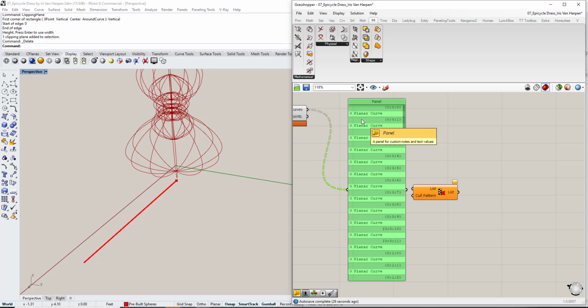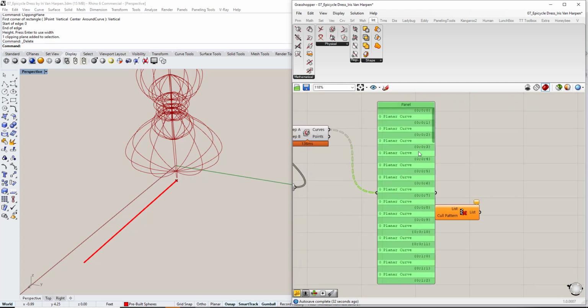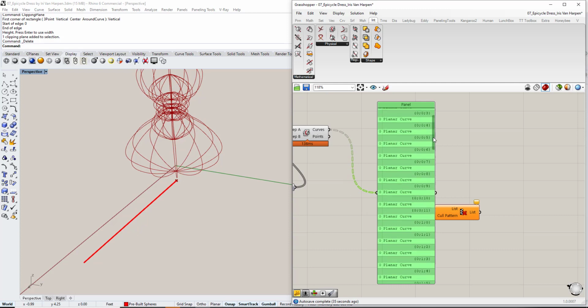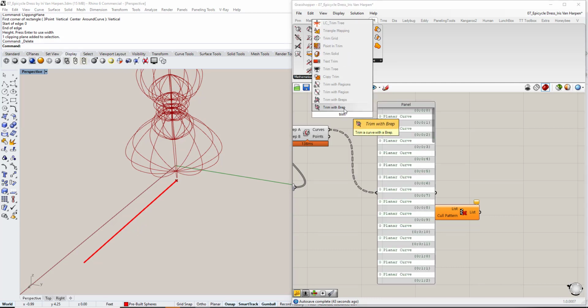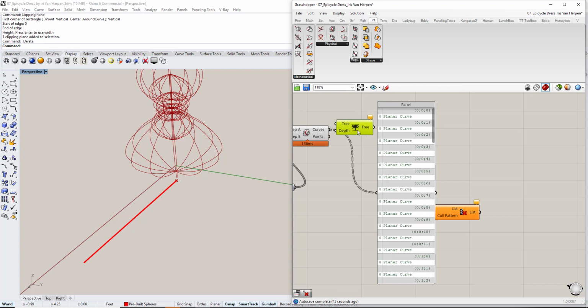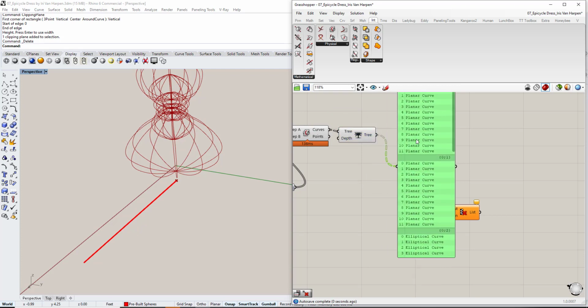I need to send it 12 curves for each of the spheres. Whenever you see this situation, almost like someone has grafted your output, instead of grafting, which will move it a layer up, you want to move it a layer down. The way you do that is you trim the tree. There are too many branches in this tree, so we're going to trim this tree to bring the number of branches down. Go ahead and try that.